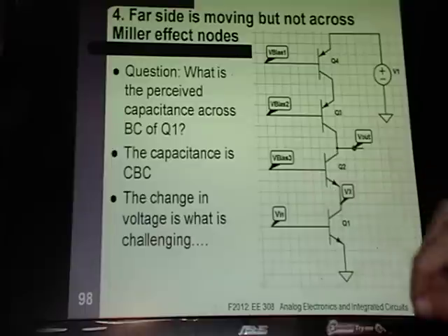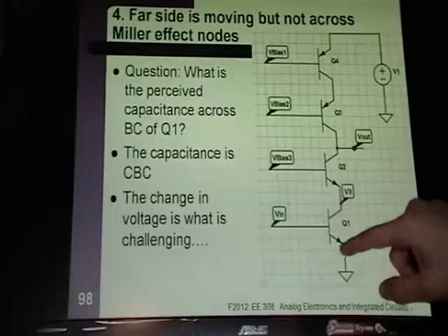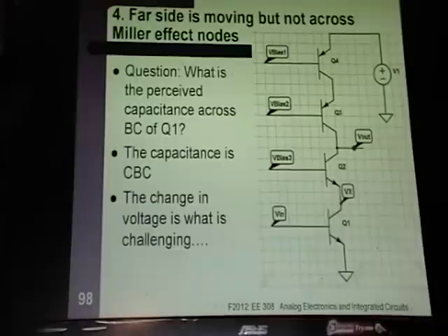If you move that up delta V, that increases the current through Q1. Assume all of these are in forward active. If the current through Q1 increases, the current through Q2 increases. Now that the current has increased through Q2, if this is in forward active, the way it's going to adjust its current...